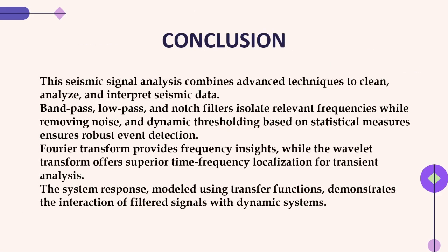In moving to the conclusion, in summary, our seismic signal analysis applies advanced techniques to clean, analyze, and interpret seismic data. Filters like bandpass, low pass, and notch isolate essential frequencies, while dynamic threshold ensures reliable event detection by adapting to noise. The Fourier transform reveals frequency details, and wavelet transform enhances time frequency localization for transient events. Finally, system response modeled with transfer functions shows how filtered signals interact within dynamic systems.